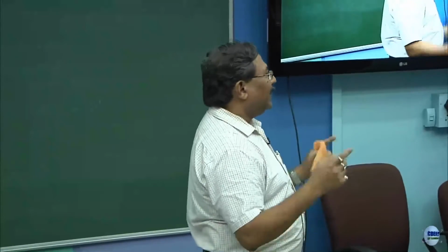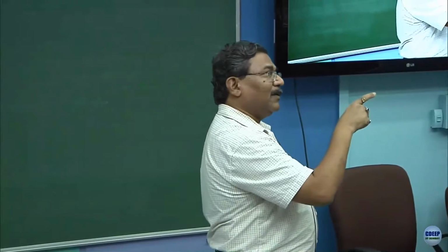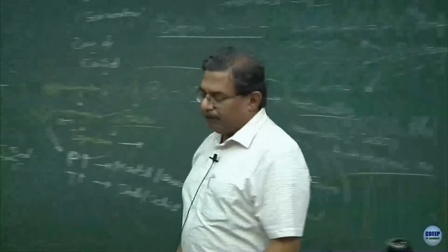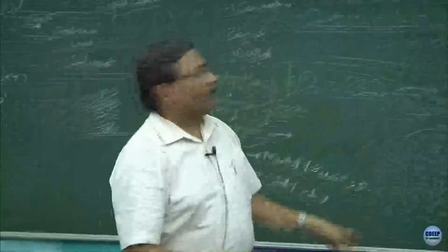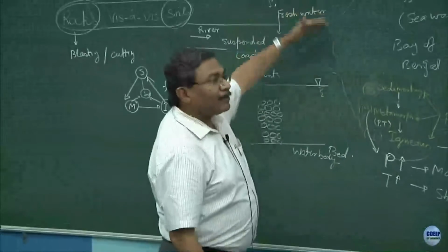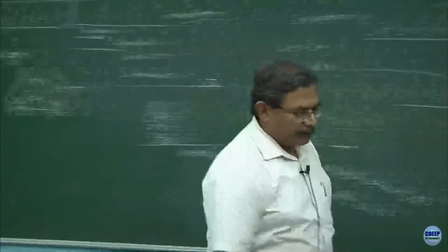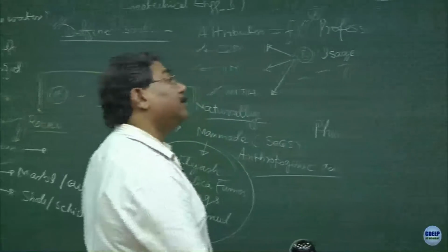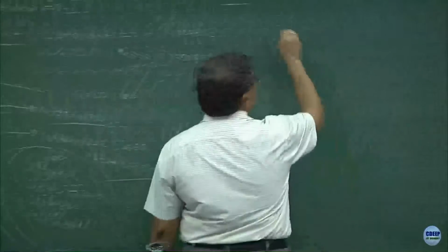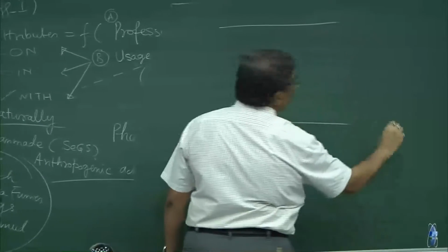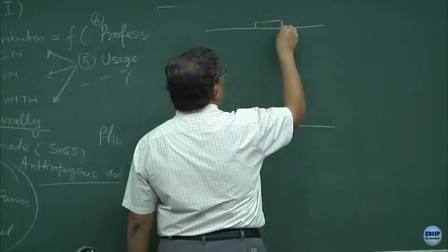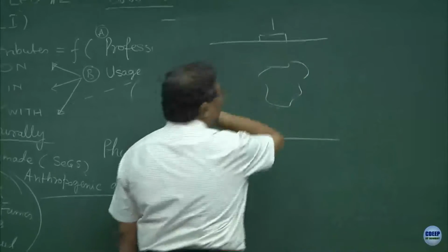These are naturally occurring processes. You can contain, you can slow down, you can retard the process. That's an engineering, that's a technology. So, if you go to Middle East, if you get a chance to work over there, Middle East is famous for having big cavities in the formations, you know, subsurface strata which I was talking about. So, a $1 million question there is, check it on net, why it is difficult to lay foundations in most of the regions in Middle East. Suppose I lay a foundation over here, you never know there will be a big cavity over here. What is this cavity?